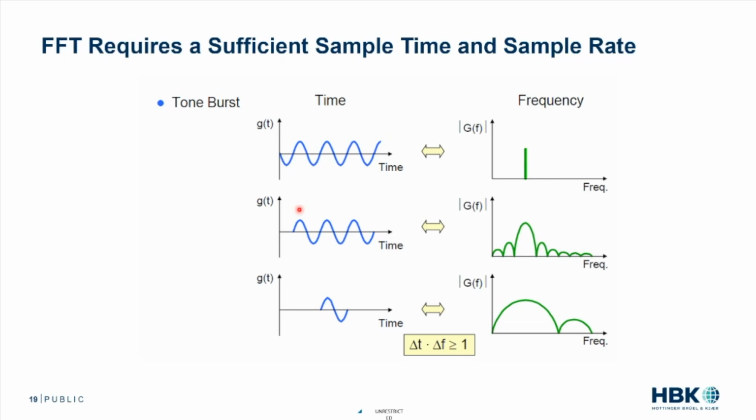Well, now, okay, we reduce that from maybe 4 sine waves to 3. We don't have as much information. The mathematical transform can't act as well, and now we see these kind of weird ripple guys centered around our main frequency. We don't have enough samples, we don't have enough time window, we don't have enough occurrences of the frequency to really say for sure it's this very specific frequency. And then we go down to 1 sine wave and we see that we barely know what the frequency is. So we need to remember, we need to have a big enough window to have several events happen because we're picking out that frequency. But we also need to sample at a rate high enough that we're not aliasing the signal, that we actually have all the frequencies of interest.